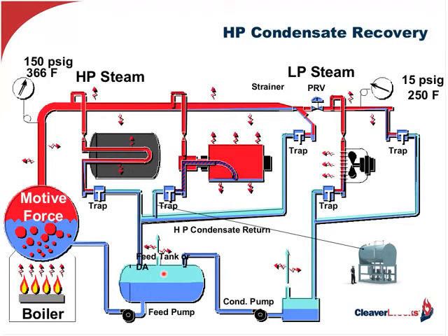Now, the other thing that we could do is we could take this condensate, if the line were properly sized, and take it back to our deaerator. But chances are that the deaerator has not been sized for that amount of hot condensate. High pressure returns, we would refer to those as. Normally if you're taking high pressure returns back to a deaerator, it can probably only handle between 15 and 20% of its capacity, or it's going to overpressurize and relieve its safety valve. Those vessels are normally rated at about 50 pounds.